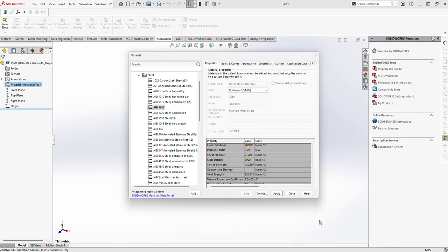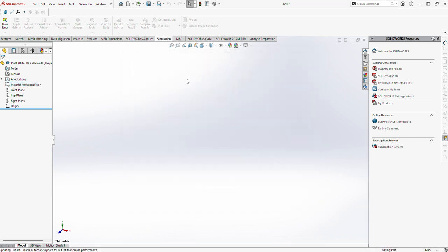Now, when we are going to create this model in SolidWorks, we'll need to make sure that all the boundary conditions are the same as those being assumed for our theoretical equations derivation. In real life scenarios, you can have boundary conditions which are representative of the real world situation, but because we are now trying to compare the theoretical equation with the simulation, we will try to keep the boundary conditions exactly the same. Later on, we can change some of these boundary conditions to do a what-if analysis.